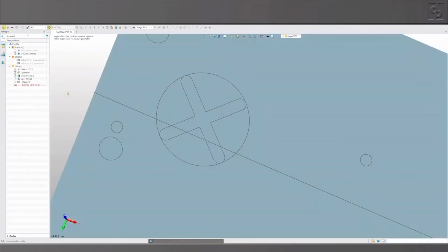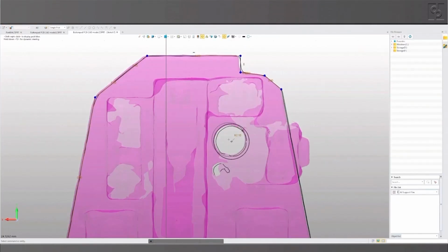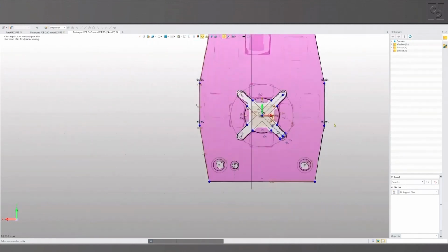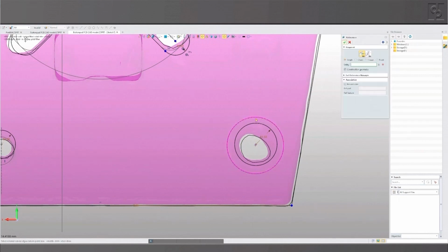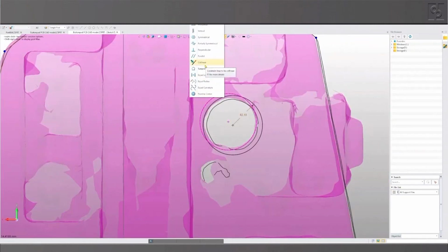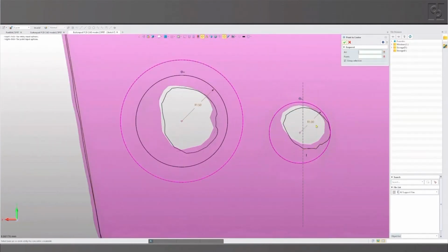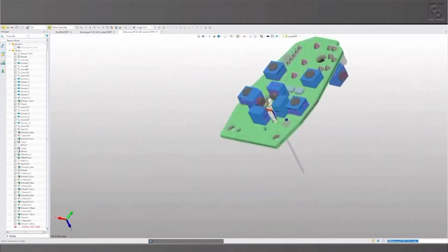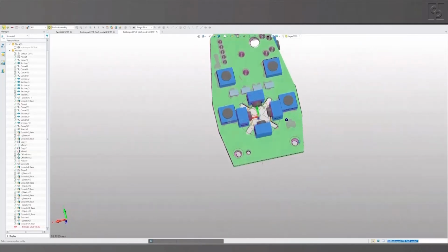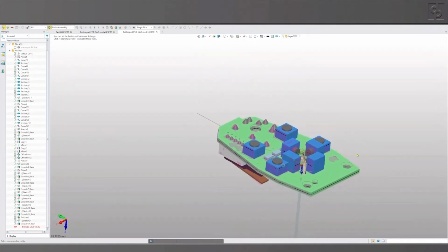So with that sketch made on the mating plastic part, we're ready to transfer the newly sketched features onto the PCB, which is still superimposed. You can see the old holes that I guessed and the new holes that I've drawn accurately, and so I'm just going to replace the incorrect features with the correct ones. Now we can regenerate the PCB package model with all the holes in the right place, confident that we can use those holes later to align with the bezel once we've constructed that.